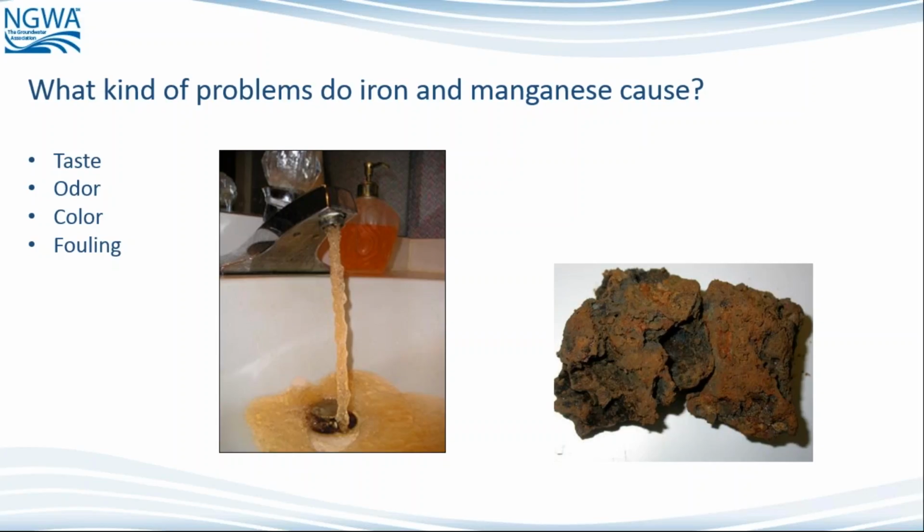And this is kind of a component of the biological formation, or what you hear us talk about, biofilm, where the bacteria have actually taken iron and oxidized it into little rust particles and incorporated it into the polysaccharide slime that they secrete. So what you can get from that, as you can imagine by looking at that deposit, you can get fouling in your well and lost capacity.